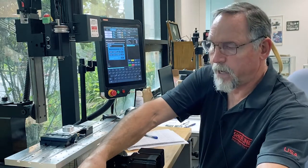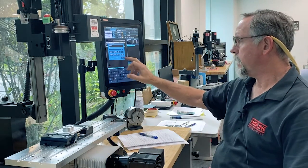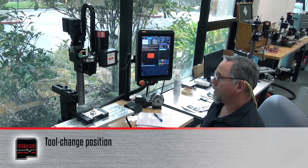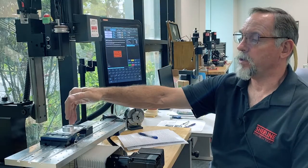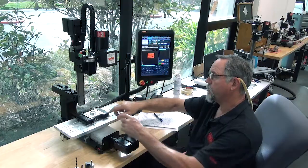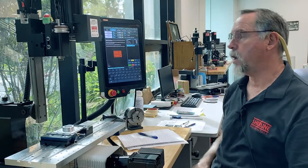With MASSO, you have several other options. The next thing we're going to go over is the tool change position. You obviously don't want your tools changing right above a part. You get done machining it. You want it to change at a position that's away so you can measure your part, blow it off, have room to take your tools on and off.